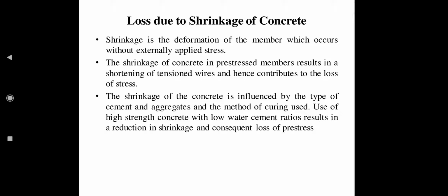The shrinkage is defined as contraction of concrete which occurs due to the loss of moisture or loss of water content during the process of hardening of concrete. During the process of hardening there is a process which occurs in the concrete which is called heat of hydration. Due to the heat generated, the moisture content is evaporated. So the concrete loses its water content or moisture content, hence resulting in shrinkage of concrete.